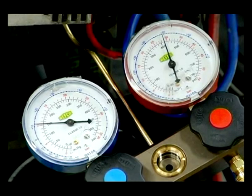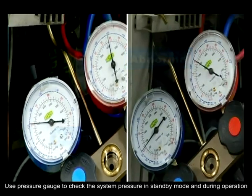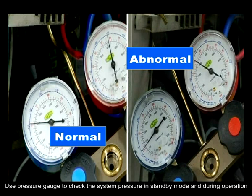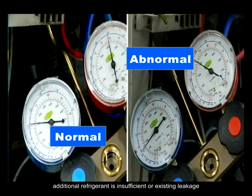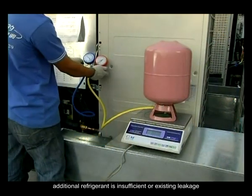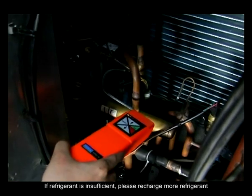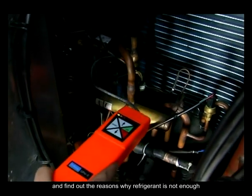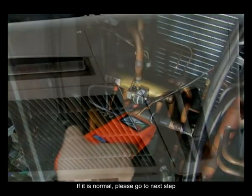Step 2. Use pressure gauge to check the system pressure in standby mode and during operation. Compare with other normal system nearby to judge if the system additional refrigerant is insufficient or existing leakage. If refrigerant is insufficient, please recharge more refrigerant and find out the reasons why refrigerant is not enough. If it is normal, please go to next step.